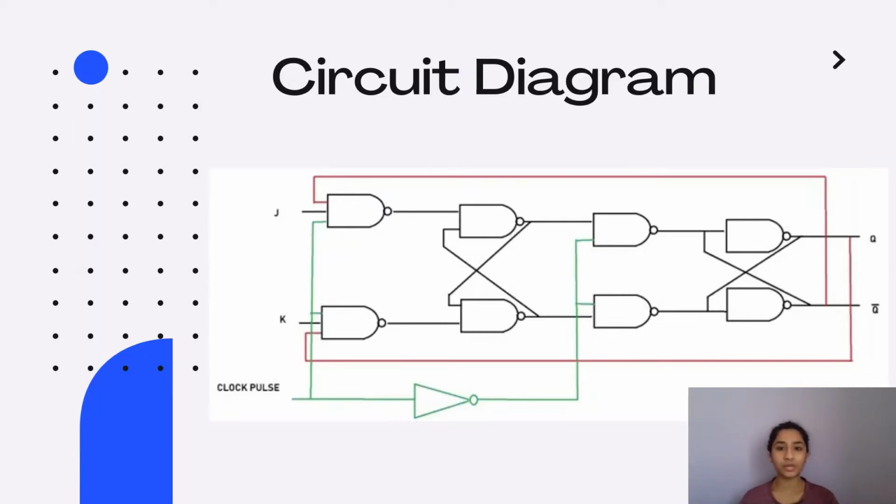This is the circuit diagram for JK master-slave, where we show what is present inside the block. In the case of JK, one thing to notice is that the output that comes out of the slave is given back to the master as its inputs, as shown in the figure. This is the only difference that we can find here.